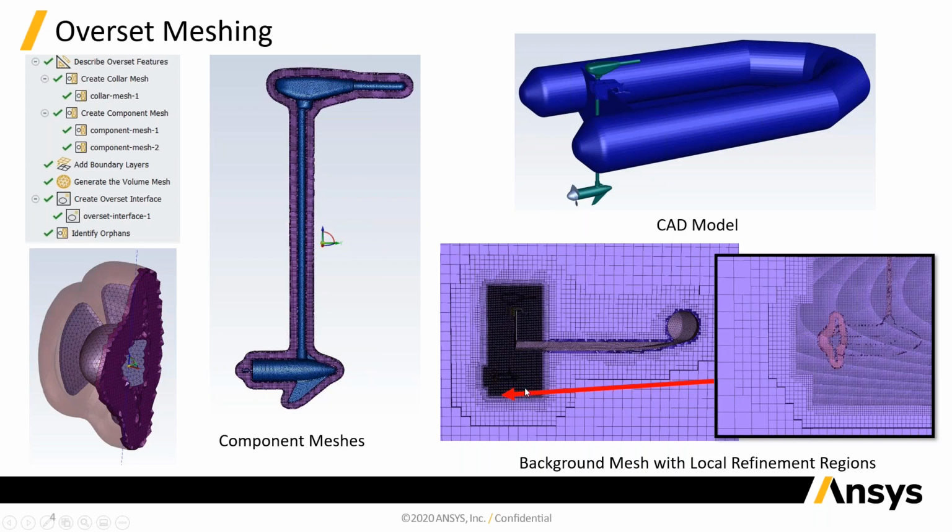And then we can overlay that on a background mesh, and the code will work out where these join, and it will have separate solutions being solved inside this mesh and the background mesh and linking them together. And there's all sorts of nice options to make sure that you get really accurate transfer between the two.